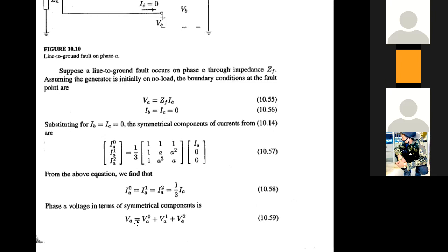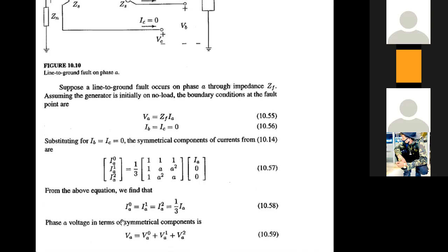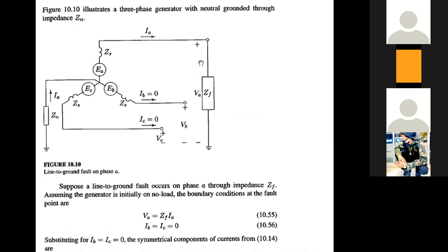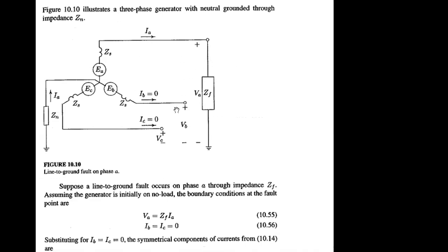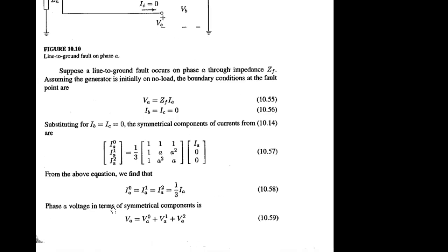Another part is the voltage. If it is an unbalanced scenario, like phase A has the current or voltage now only, that means we have an unbalanced scenario. We don't have the same information for all the phases. Only VA has the information of voltage over that fault impedance ZF. So VA will be the unbalanced voltage, and that can be resolved to its equivalent 0, 1, 2 domain.